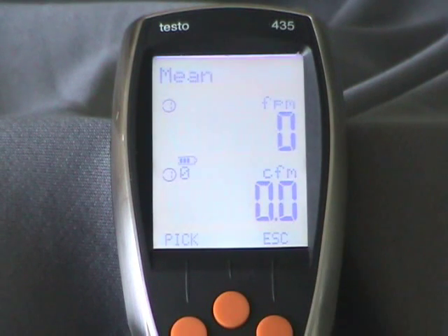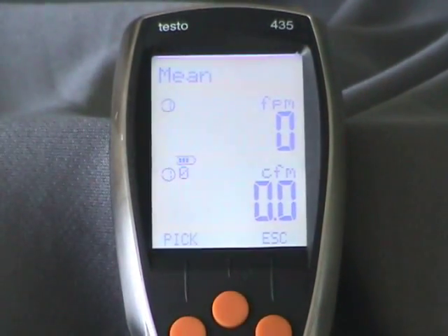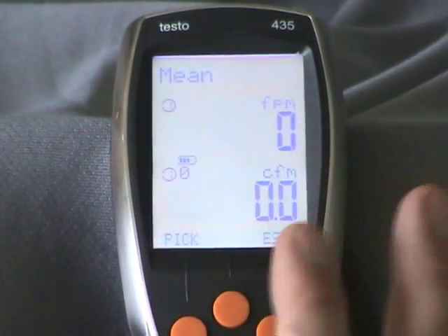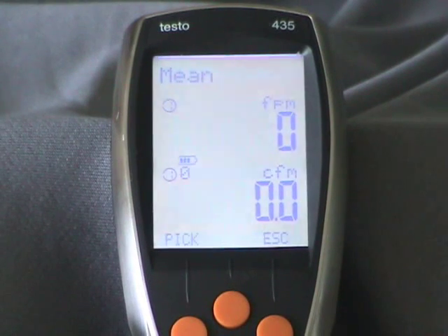And what that is, you choose the location on the grill where you choose to take the measurement. So generally I take 3 or 4 measurements per row of louvers in a return air grill. If there's 3 columns, then I'll go down that column and take 3 or 4 measurements. Obviously the more the better, but that's what I do. And then you take the first one and then you walk over into the bedroom where the next return air grill is, and you do it.